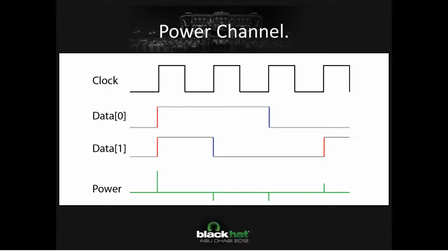Here, let's look at two of the data lines on a data bus. Different devices could have different widths of data bus. If we have a small microcontroller, often this means an 8-bit data bus, but your larger computer will often have 32-bit integers, which means a 32-bit or 64-bit standard data bus. And if you have really odd systems or specially designed hardware, this data bus could be wider too.